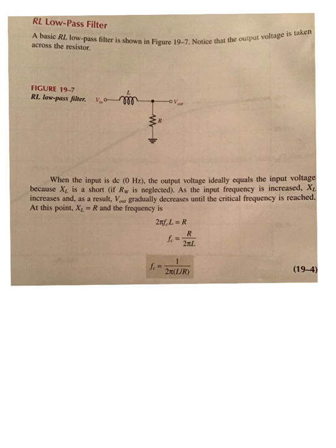Okay, here's a low-pass filter, but it's built with the resistor over here, and to get away with that, we have to throw the inductor into the equation for it to work, and we need a different equation for the cutoff frequency. I'm not going to dwell on this too much. I'm just going to tell you that at very low frequencies, the inductor is nothing but a wire, not an open, a wire.